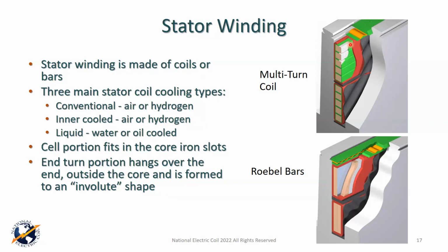So we've got strand insulation, we've got turn insulation. The red that you see here in this picture is the ground wall insulation. Now, we mentioned a term earlier called VPM, which stands for volts per mil. Pretty simple, really. It's the voltage potential to ground over the mils of insulation. And the higher that number, the more electrical stress you're putting on that ground wall insulation.